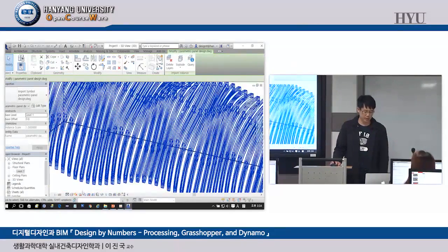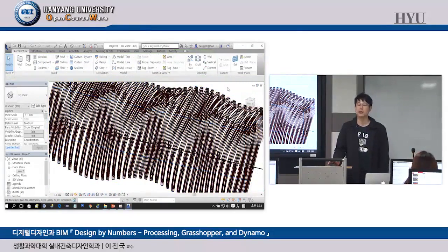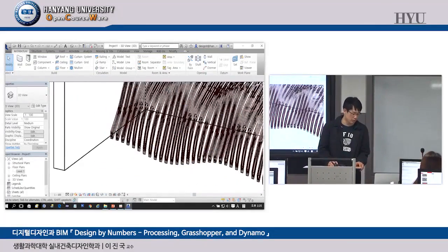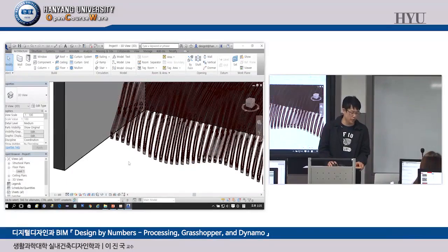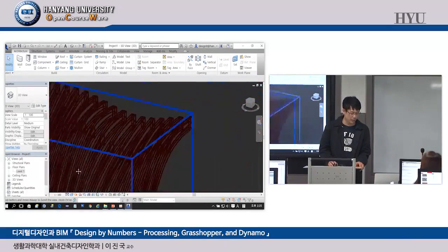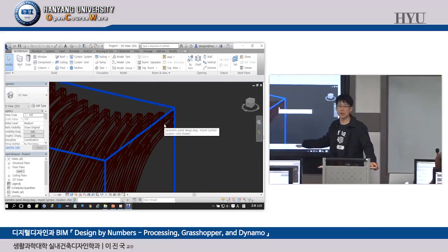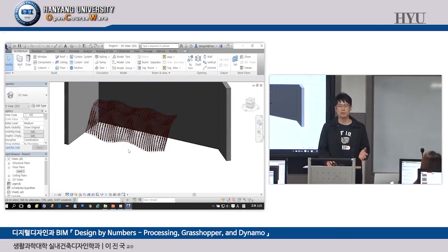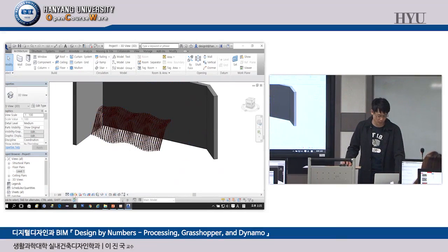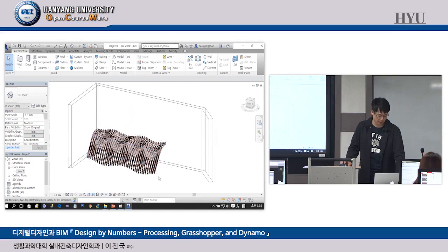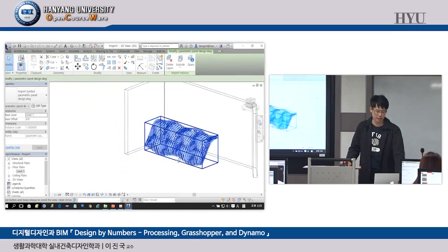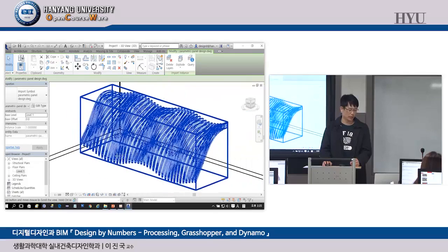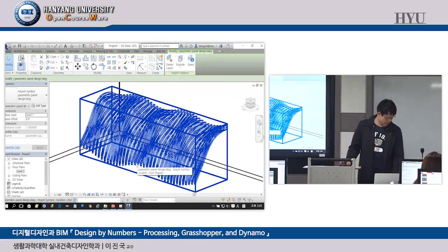Take a look. This geometry is kind of hollow, okay? This is DWG file, which means surface-based 3D. So this is not good, okay? Even if you change shaded view, take a look. In this view, they are all just lines, okay? Simply because you imported DWG file. DWG file is not 3D. So, in other words, this geometry is kind of ill-defined geometry in terms of Revit, okay? Revit always uses solid 3D.